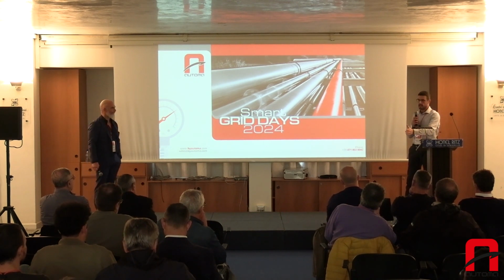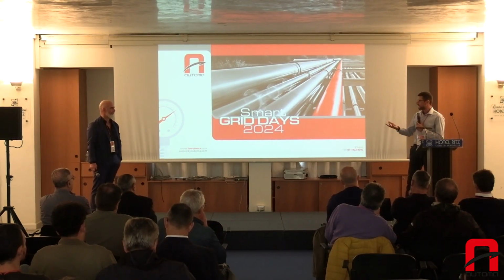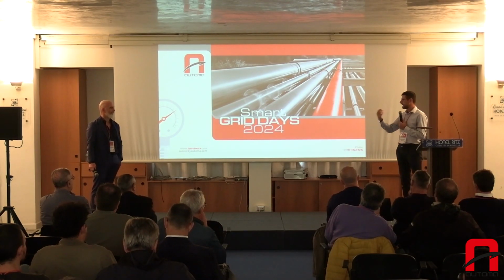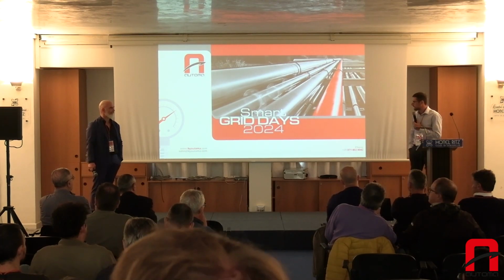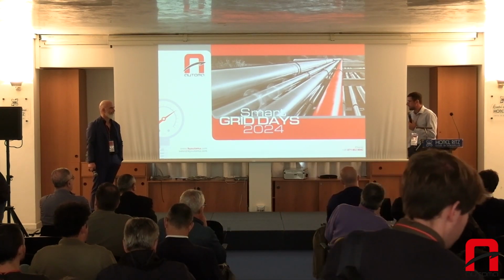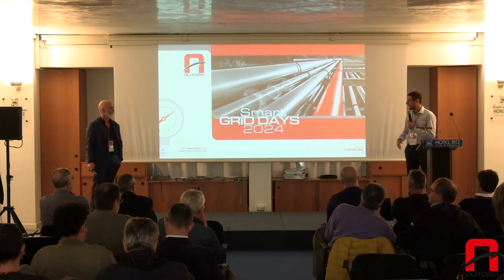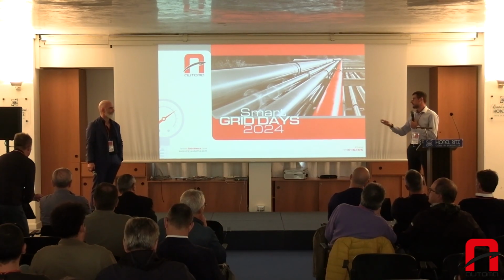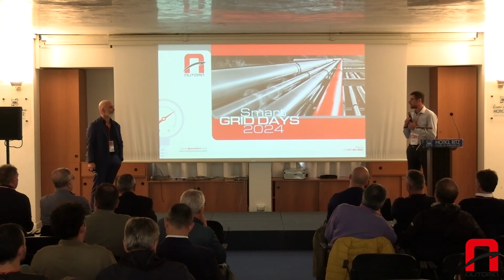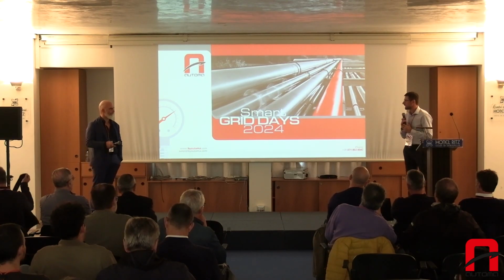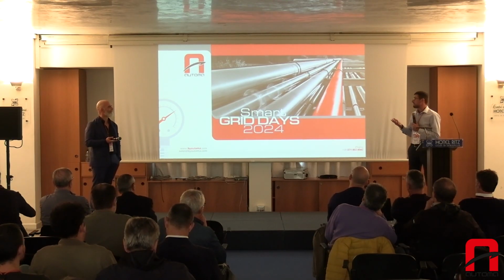So actually, with cathodic protection, I can only stop the rust, or I may decide basically to do some repair works. As for the continuity, that's fundamental. So far, we have not used special methods, but on site, we carry out continuity measurements with a simple traditional tester.